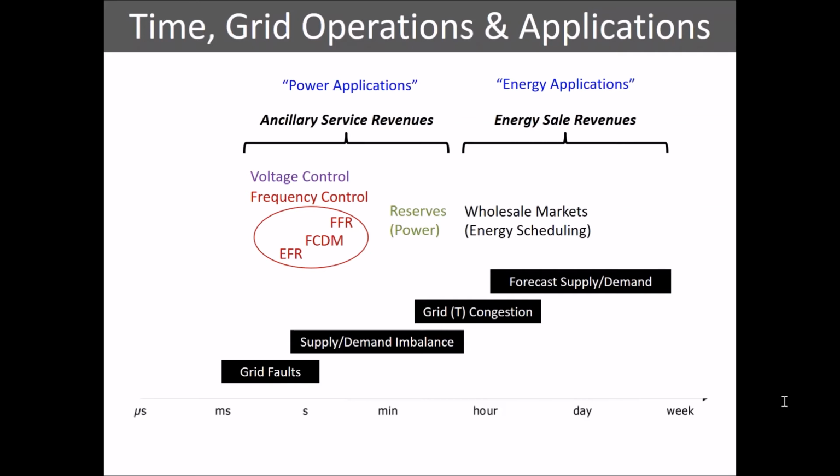Now that frequency has to be maintained at all times across the entire system, and basically frequency varies if there's a difference between the power being pushed into the network and the power being extracted out of it by end users. If you're pushing more power in than is being driven out, the frequency goes up. If you're trying to suck more out as an end user than is being pushed in, the frequency will drop. And system operators have to keep that frequency within very tight tolerances, within very small limits, and they do that because those things can happen on very short time frames by having systems in place, and in particular conventional power plants in place that can adjust their output very quickly, anything from down at the second, ideally sub-second time frame, up to, for frequency control, tens of seconds.